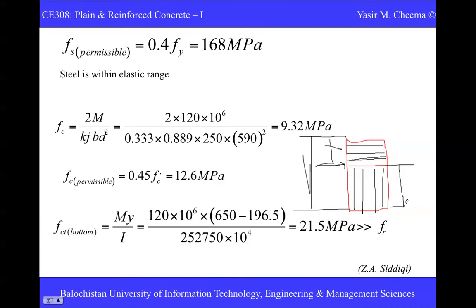I hope you can just find out how much this depth is. Further is the moment of inertia, I think we have calculated previously. So just using this relation you can find the tension stress here, in the loaded structure. If you see here, it's compared with the modulus of rupture value that was 3.5 megapascal given in the question. So it is much more than the modulus of rupture.